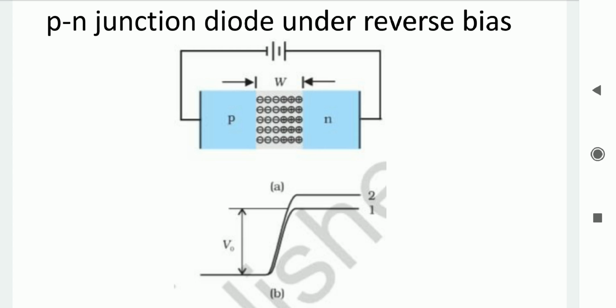So this condition can also happen if the diode is in forward bias, and if we continuously increase the input voltage beyond its limit, then the forward current exceeds its limiting value, and in forward bias condition also overheating will produce, which can damage the diode completely.